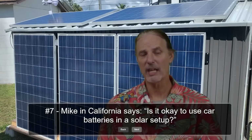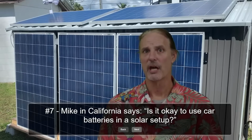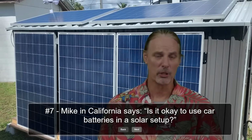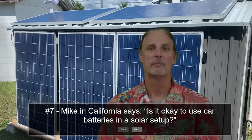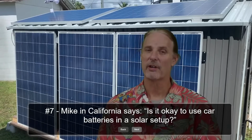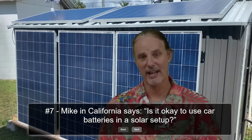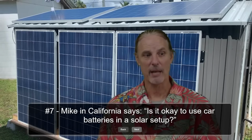But definitely you can use them. They just have a whole variety of other problems that you need to deal with. You need to make sure you keep up with the water. You need to make sure you keep up with maintaining them, and you need to be very careful about discharging them too far, because when you discharge a lead acid battery too far, it damages it.